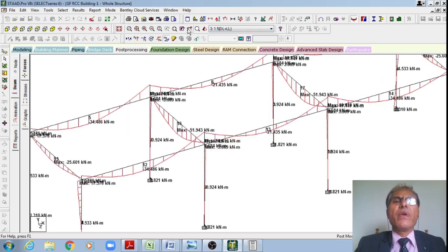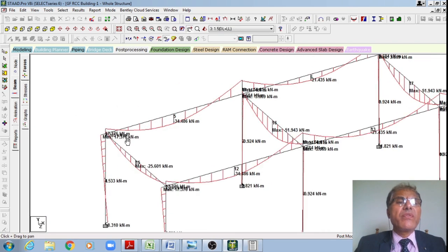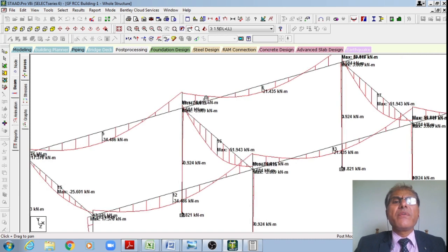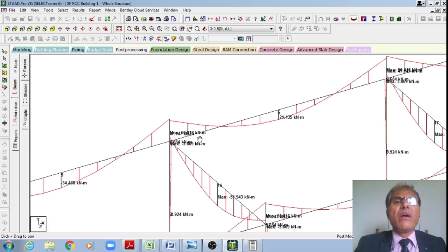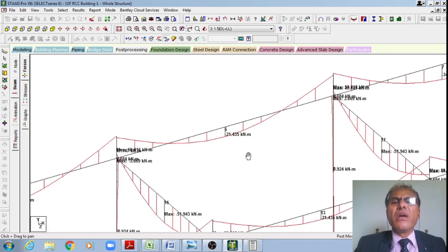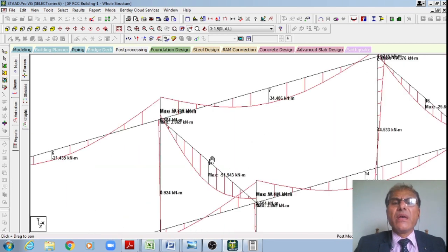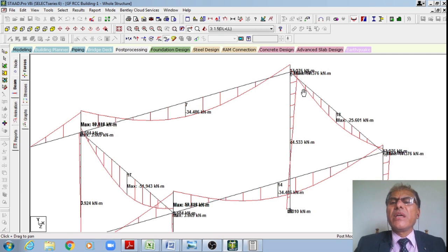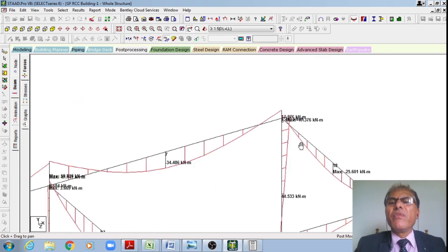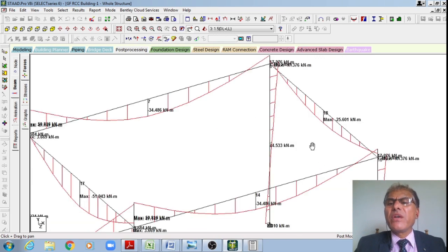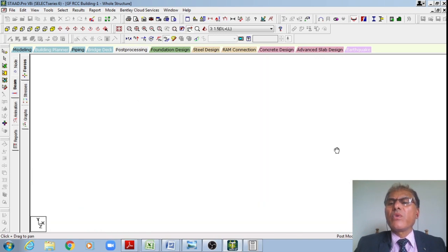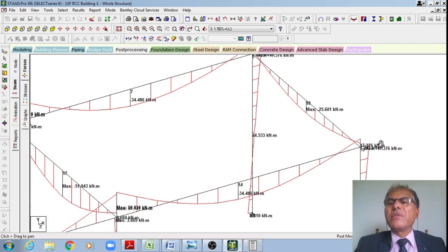It is varying. The negative bending moment is varying from this 17 to 34, positive to the top 50 to 21 to some 50, 34 to 37, like that, right? Whereas for the exterior beams, it is 0 almost, varying from a small value of some 7 to central moment 25 to that of say 17 kilonewton at the end, right?